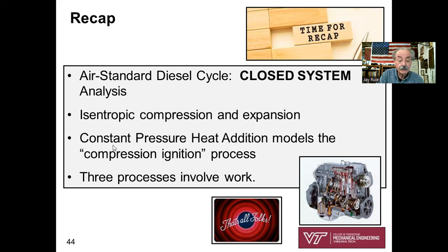For the diesel engine, the constant pressure heat addition and expansion model is what models the compression ignition process. For the diesel cycle, three processes involve work. On the Otto cycle, there are only two processes that involve work, and you can see that in doing your homework problems. But for the diesel, three processes involve work.